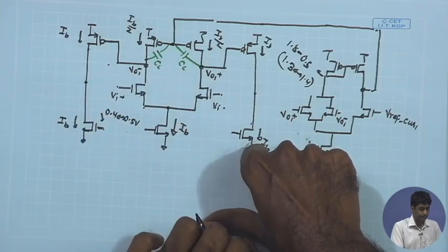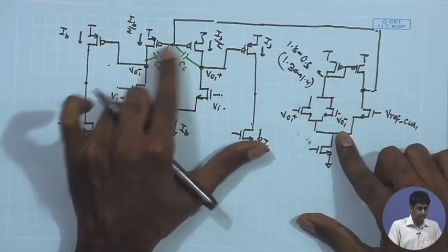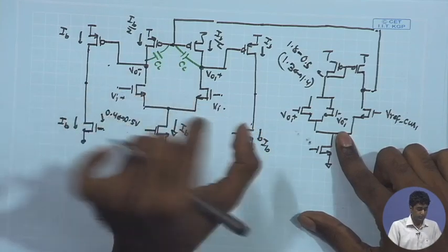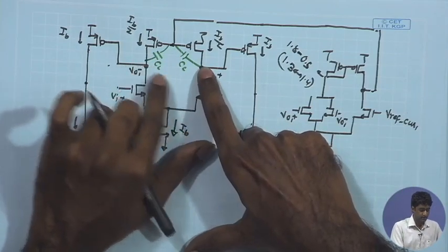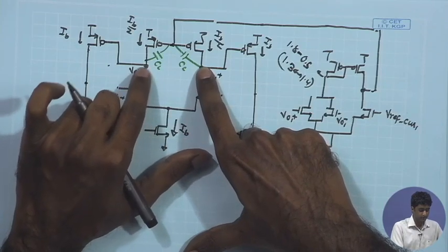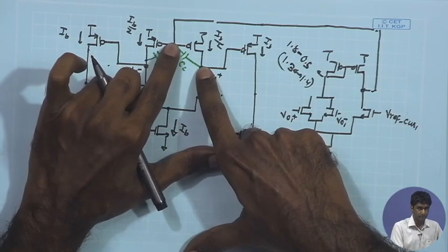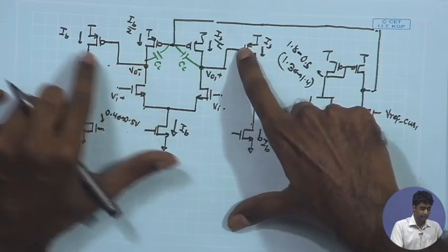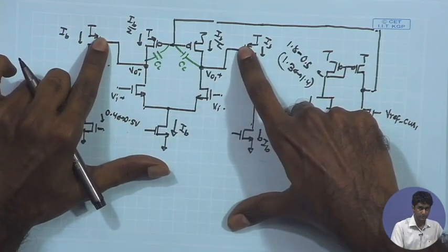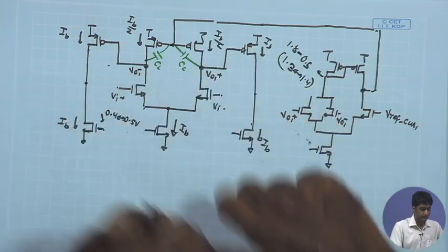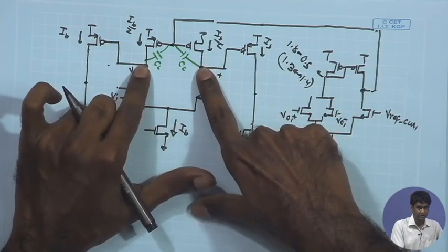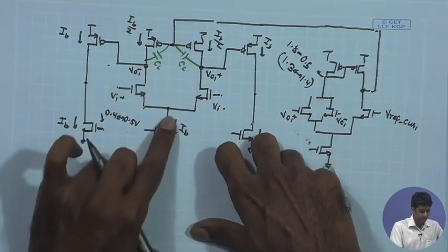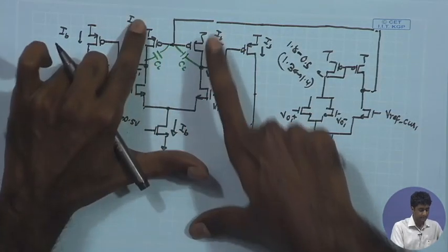over here. So, if you have a single ended op amp where the first stage is diode connected, there you directly have an assurance that the output DC potential over here will be dictated by the gate potential of the PMOS, and that also becomes the input DC point of the PMOS of the common source stage. But in this case, the output DC point is not defined. The gate potential over here is expected to be such that it supports the same IB by 2, IB by 2